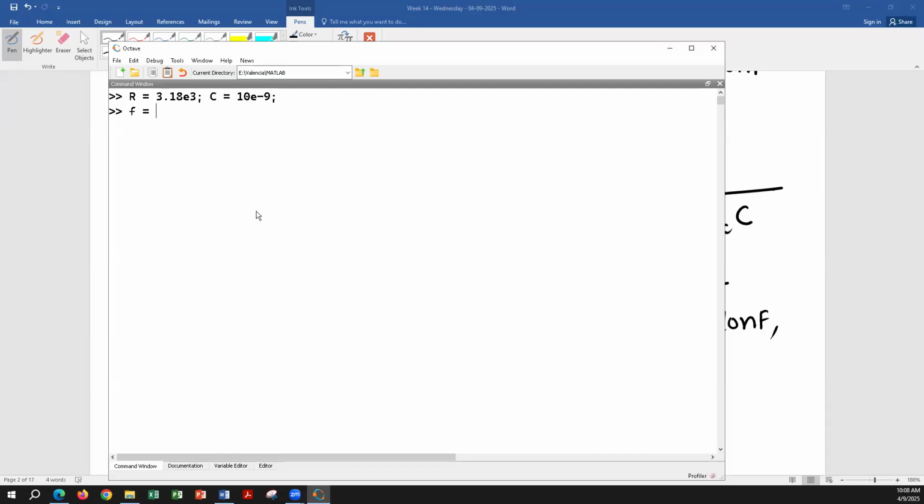So generally you can go from, let's say, 0.1, instead of starting at 0. Since our cutoff frequency is 5 kilohertz, we want to go at least, so 5 kilohertz, next is going to be 50 kilohertz, and then 500 kilohertz. So let's go to 500 kilohertz, and let's increase our interval to 100 hertz, and go to 500 kilohertz.